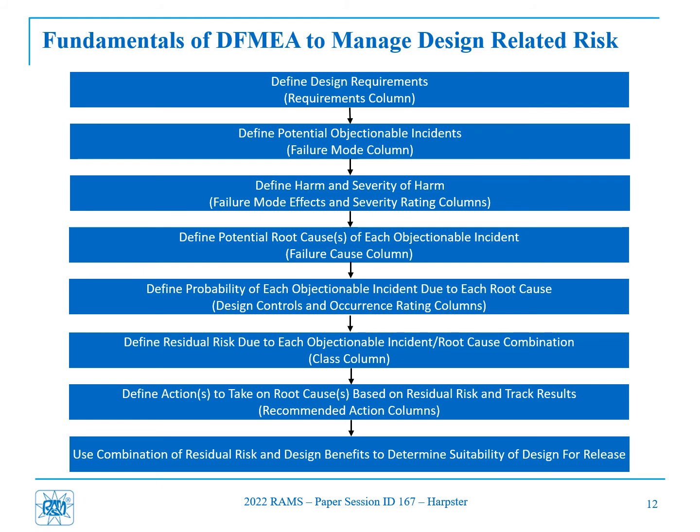Once we identify the failure mode and the harm, the next step is to identify the root cause. And it's very important when defining the root cause of a particular failure that you either define a hardware spec that has been incorrectly set, or you define software code that has been improperly written. Those are the only allowable entries in the cause column of the design FMEA. We're going to see that both the AIAG-VDA and SAE J1739 violate this basic principle.